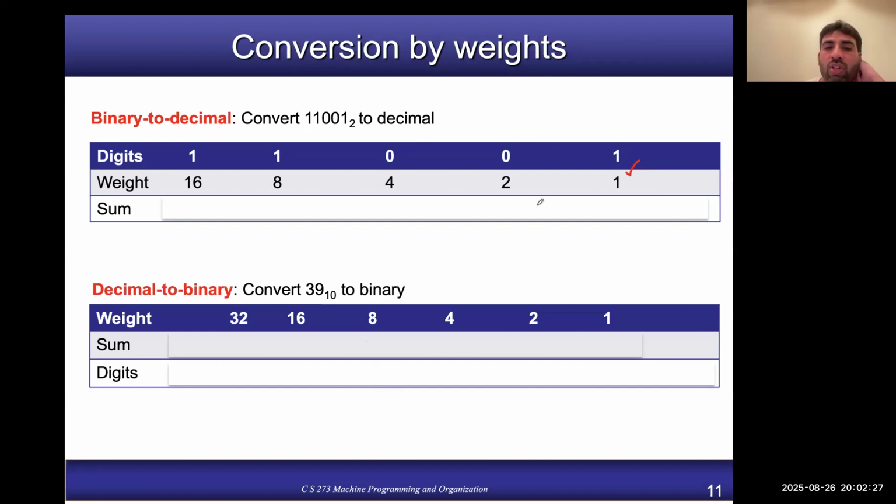So in all the locations where I have the corresponding binary digit as 0, I simply ignore them. For the remaining ones, where the binary digit value is 1, I can add those weights. So basically I can add 16, 8, and 1, and ignore these others because the binary symbol is 0. So I come across 16 plus 8 plus 1, which is equal to 25, right?